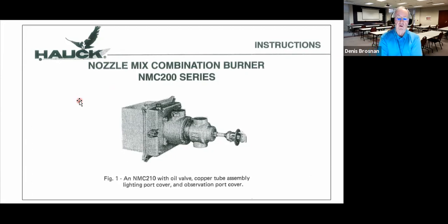And this bulletin gives a lot of information, particularly the air volume requirements, gas volume requirements, pressures that are required to maintain a stable flame, the burner output, as you can ramp up the output using more and more air as the air and gas are changed in volume as they're injected into the burner to get more heat. We'll talk about that in the burner control section of a later lecture.